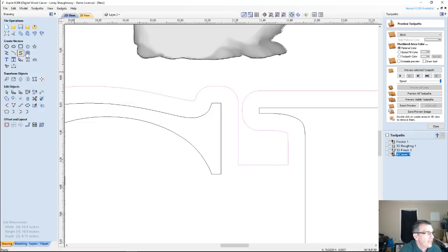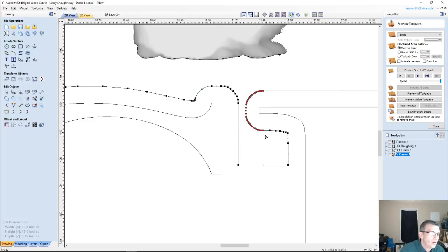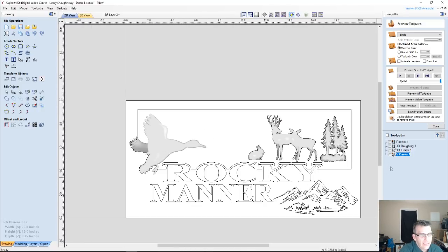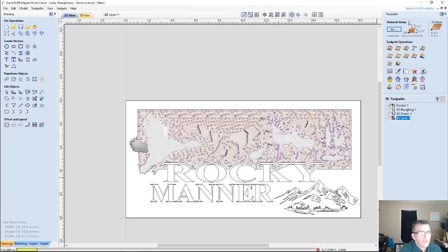So now I can adjust that if I simply take these nodes and move them over a little, widening that gap, and possibly these nodes, widening that gap, and I recalculated the toolpaths, more specifically my pocket toolpath, really.